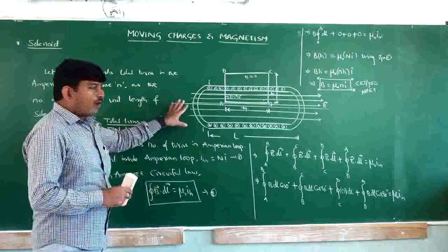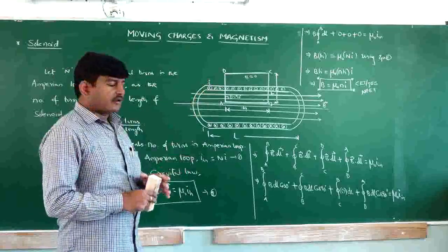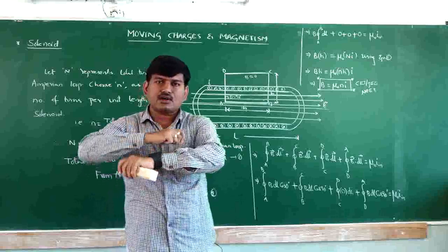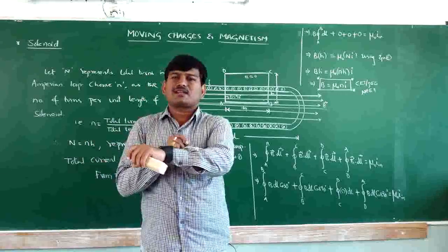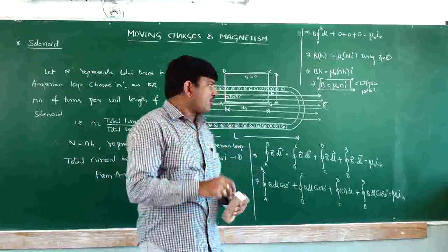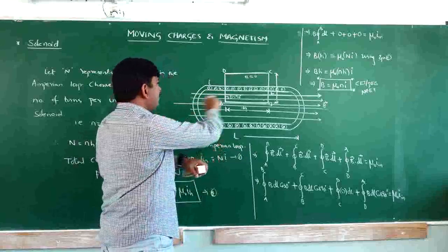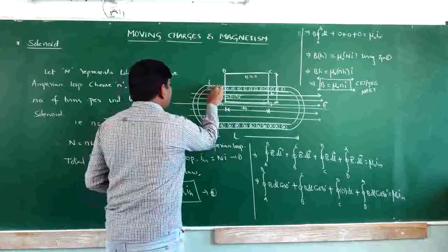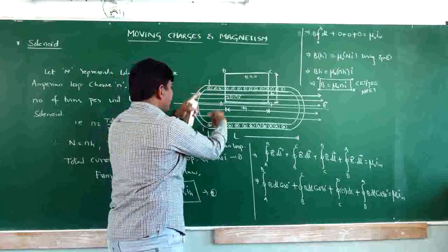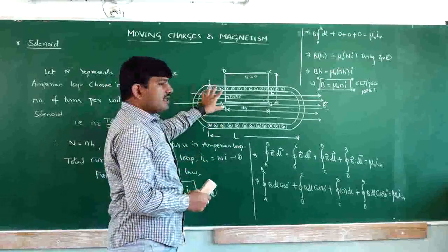So, why must it be insulated copper wire? If it is not insulated, when the windings are close to each other, the copper wire is conducting, therefore the current won't pass through the turns, but the two turns will be coming in contact with each other, and the current won't pass in this way. That is why it must be insulated.